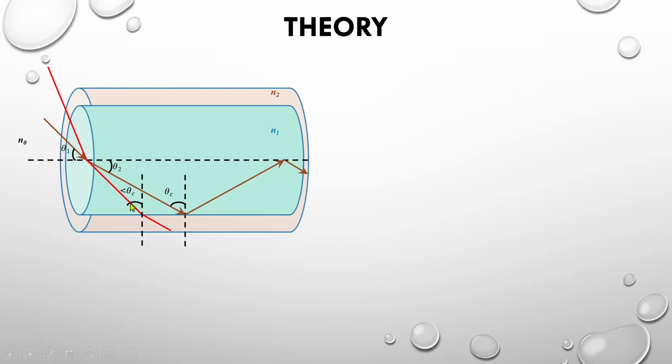As the total internal reflection condition is violated, this ray is eventually lost by radiating out of the fiber. It indicates that beyond a certain maximum angle, say theta max, the condition of total internal reflection is violated. Thus, the maximum angle at or below which the light ray undergoes the total internal reflection to propagate through the optical fiber is known as the acceptance angle.